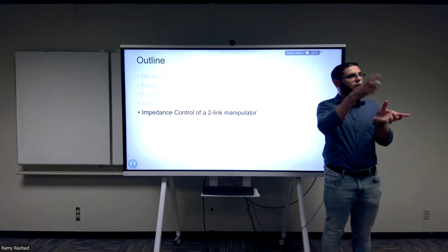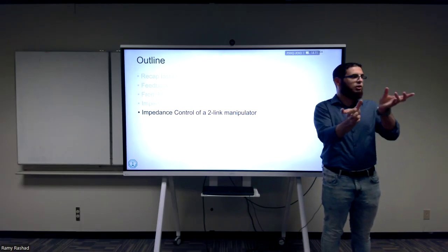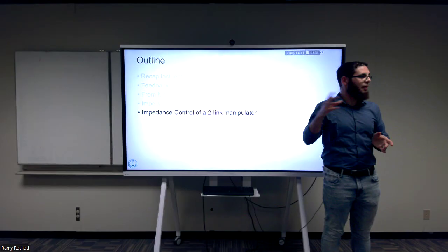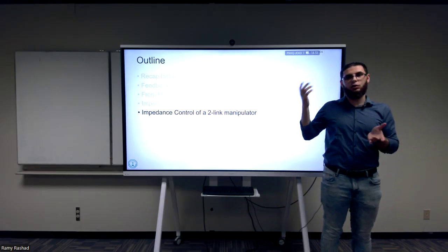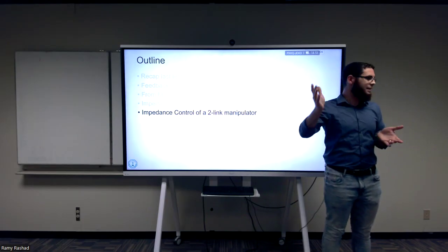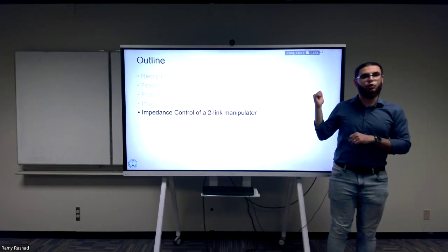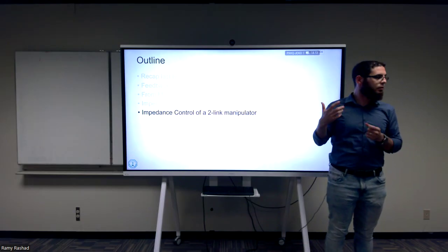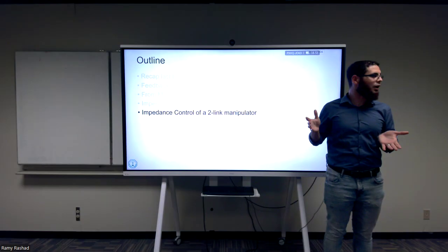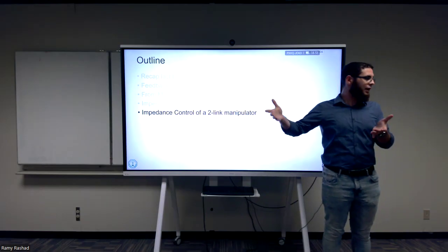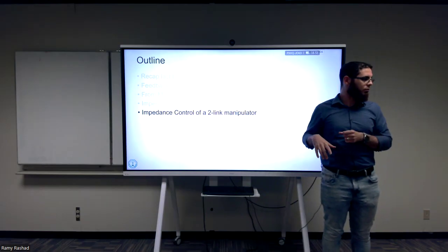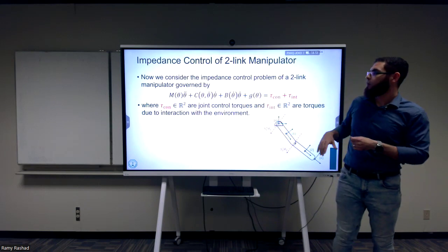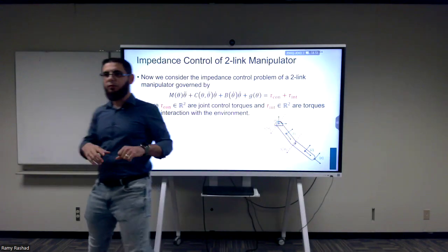Last time, the control was just the proportional term and the derivative term. And the gravity compensation was, even in the feedback linearization, also there, so we canceled out the gravity. We're going to be doing the same here. When we look at the N-link manipulator or the two-link manipulator, we're also going to cancel out gravity, and then start thinking about whatever extra controller you want. So this is now the equation that we have, slightly different.